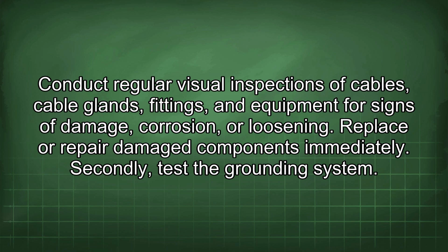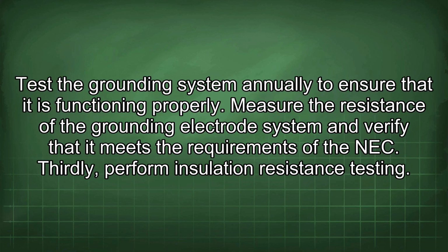Secondly, test the grounding system. Test the grounding system annually to ensure that it is functioning properly. Measure the resistance of the grounding electrode system and verify that it meets the requirements of the NEC.